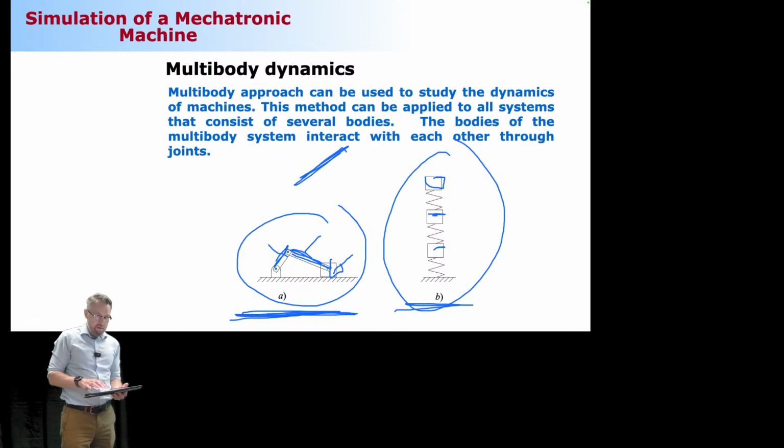So now, if I take hold of the piston body and move it back and forth like happens in a combustion engine, the rest of the bodies will follow accordingly. And you can solve this position using something called kinematic analysis, using just motion and velocities. If you take hold of this body and compress it downwards, you cannot solve the position of the neighboring bodies by using kinematics, simply because they are connected using forces. Forces are spring elements that are located here.